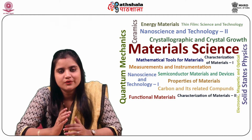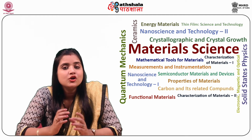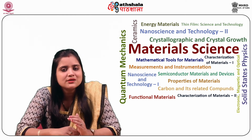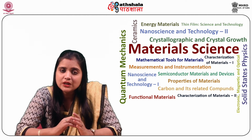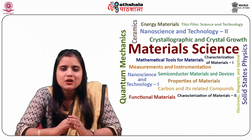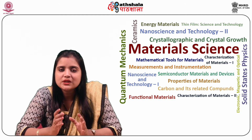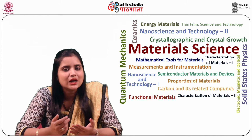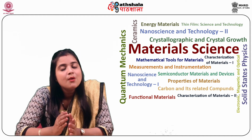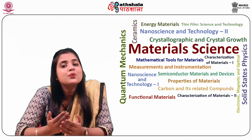magnetic field and current. The Hall coefficient is defined as the ratio of induced electric field to the product of current density and the applied magnetic field. It signifies the characteristics of the semiconducting material, as its polarity depends upon the type of conduction and its magnitude depends upon the carrier density and properties of the charge carriers that constitute the current. In the case of semiconductors, the charge carriers are generally both electrons and holes that may be present in different concentrations and have different mobilities.